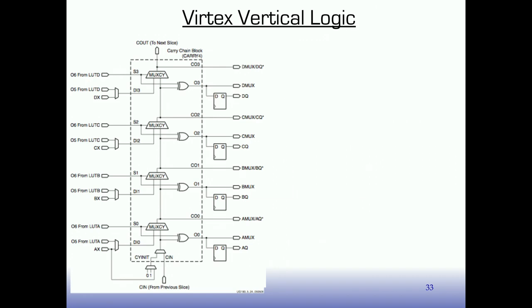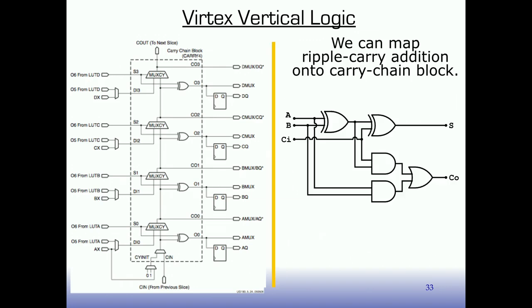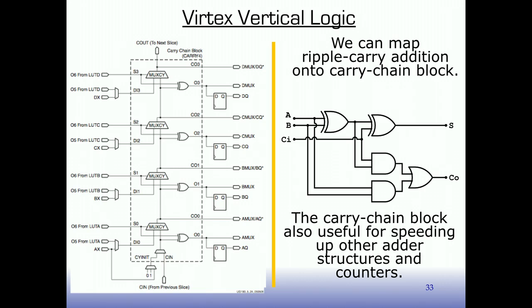they've built in special circuits that implement the carry chain, that rippling of the carry through the adder. So it can make adders, and show the details here, we'll talk about it more later, but this is extra logic that's in there specifically for speeding up circuits like adders. Incrementers and counters are another example of what gets sped up like this, or comparators can also use this logic. So kind of these iterative serial sequences in space can be sped up with this special logic. And like I said, it's incremental addition to the size of the LUT, but it actually speeds up a lot of circuits dramatically.